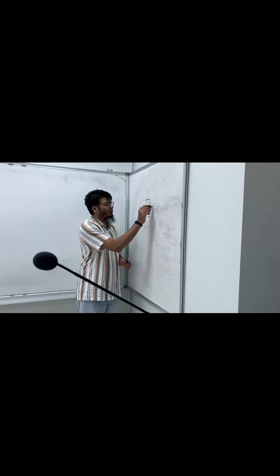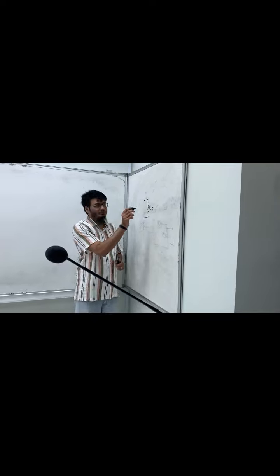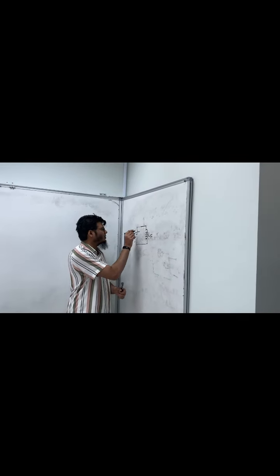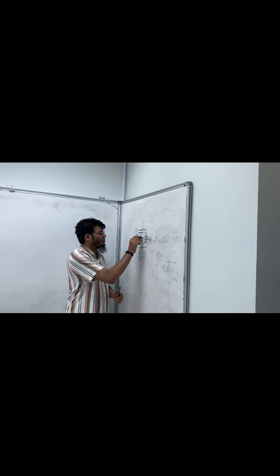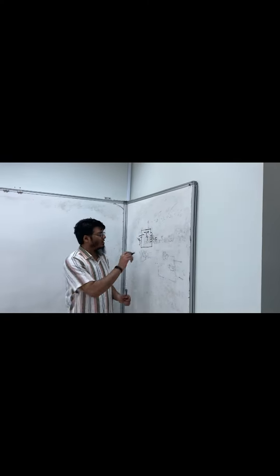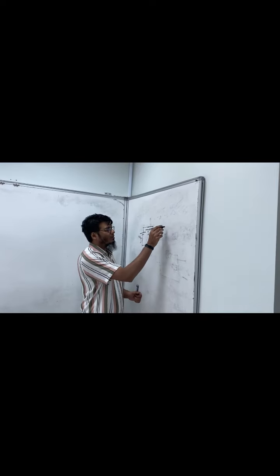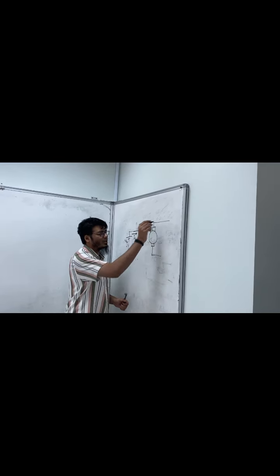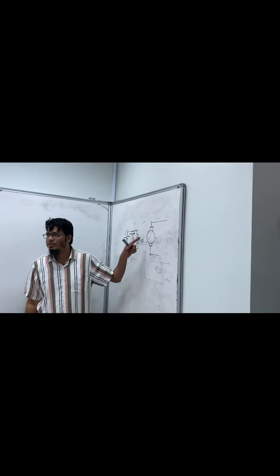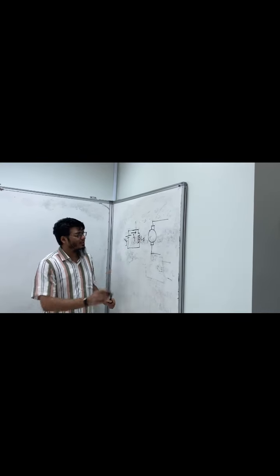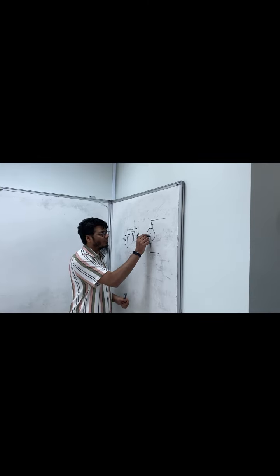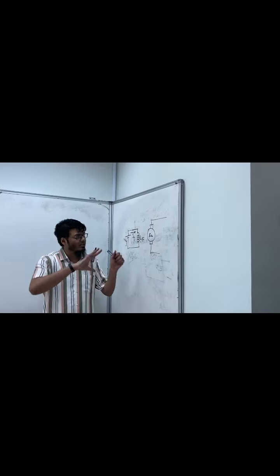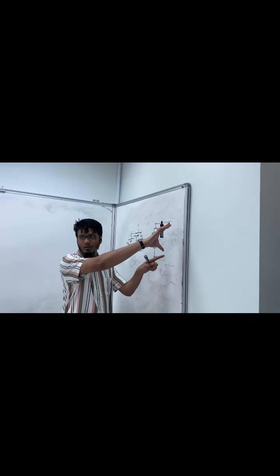This is LF, inductor of the field, and we apply a particular voltage, which is VF. Because of that, this IF flows, right? And whenever there is a field, this armature starts rotating. And inside this armature, the voltage EA gets generated, and it starts giving the output. We connect our load over here, right?